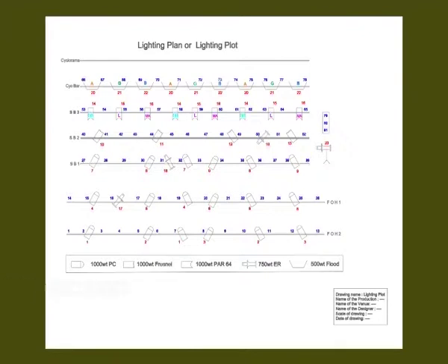Now see the channel numbers from 1 to 9. These are for general area lighting. From this, it is quite clear that the performance area is divided into 9 areas. You may ask why these are denoted from 1 to 9 and not from 11 to 20. Proper sequence in distributing channels will always help you during the execution or operation.